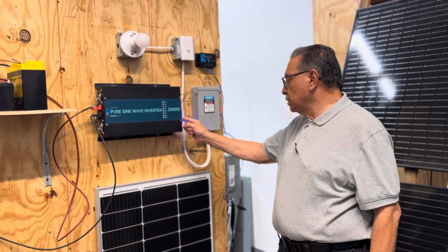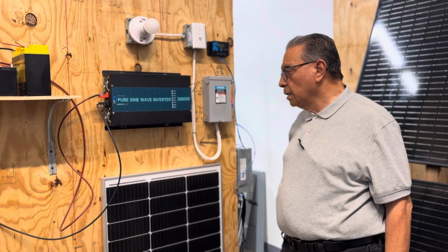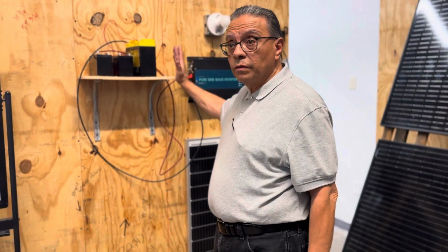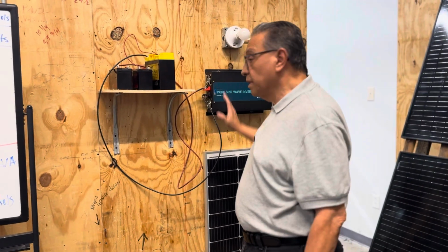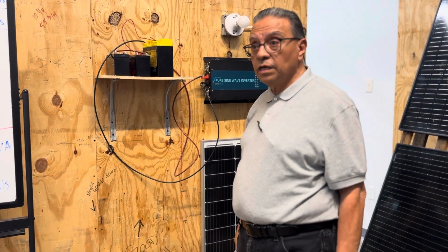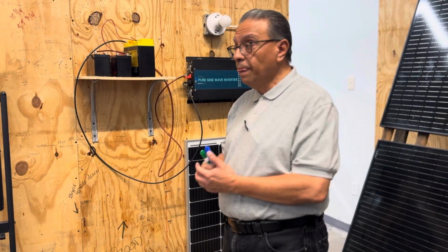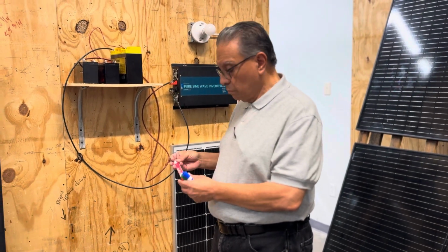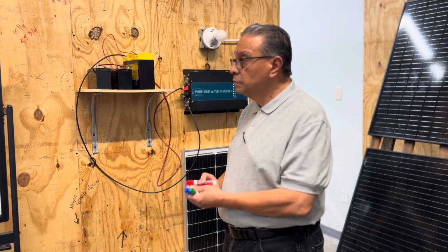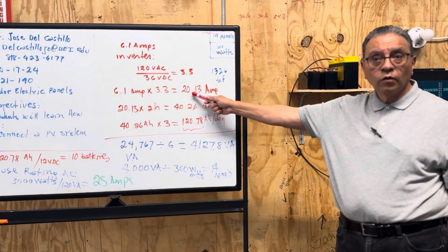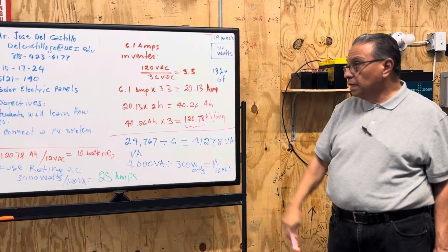And I disconnect this. But there is something missing here to have a safety system, protection before the inverter, to protect the inverter at the input. So I need DC fuses here, okay, DC. This will be the side for my fuses at the input.